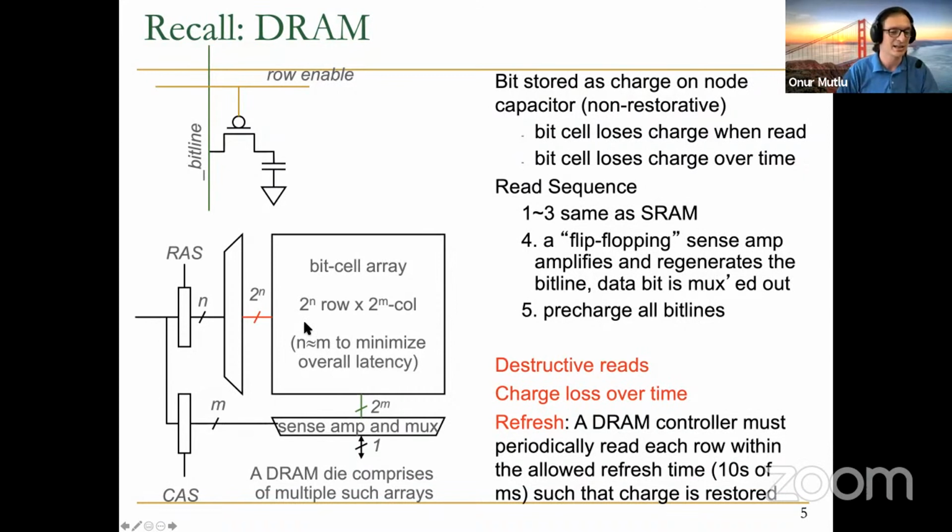As a result, a lot of the design decisions made in DRAM chips are dictated by the cost of the DRAM chip, as well as the cost of going off chip, the pin count, for example. And we said that you cannot provide the full address to a DRAM chip. You just provide the row address first and then the column address. We also said that the data output is also smaller. You can get 8 bits, for example, or 4 bits or 16 bits in existing DRAM chips.